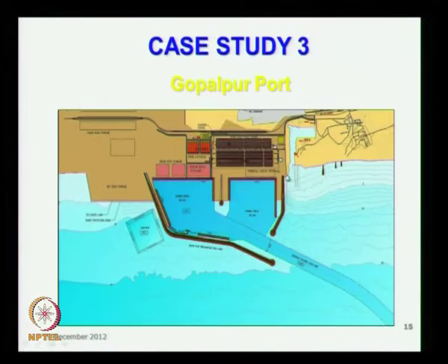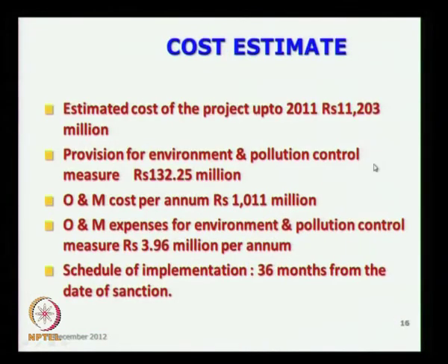Suppose you have the north breakwater here, at 2 km away from this it will erode by 20 meter. So this accretion will be like this. So accretion will go like this. At the root of the breakwater it is 140 meter. As you go towards the southern side it will get reduced. Similarly erosion may be more here, but as you go about 2 km the erosion is about 20 meter per annum.